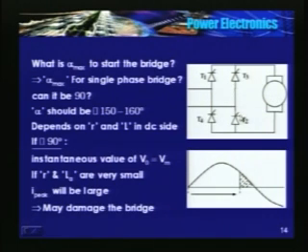Prior to triggering these devices, there was no current. So if you trigger the bridge at alpha equal to 90, the instantaneous value of Vn is Vm, the peak value. So your peak voltage you are applying to the motor terminals, if it is 230, you will get around 320 or so. At 320 volts, current is limited by R and a small L.